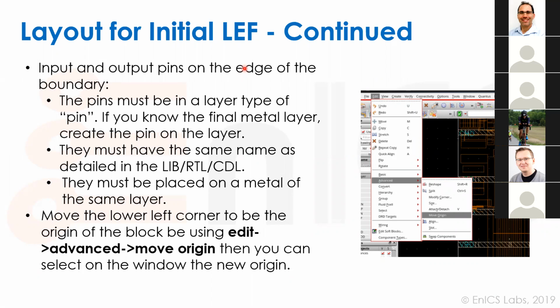Because this is how we connect to them from the outside. Power pins. Actually, this is not a must, but we want to leave the tool less possibility to do stupid things, because when they're on the edge, the tool doesn't have too much choice and connects from the edge. When the pins are in the middle, the tool can consider multiple ways how to do it, and for sure it will make an error.